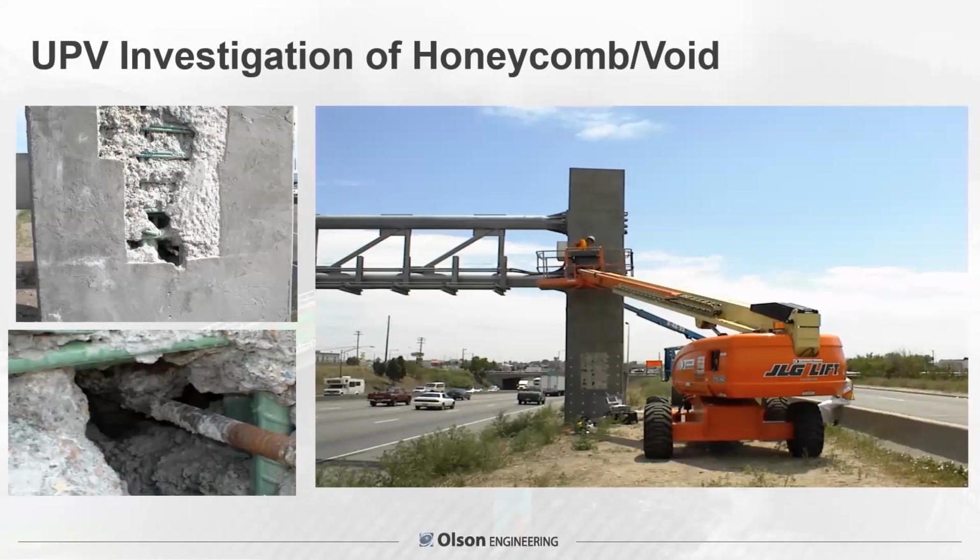So 33-foot tall, 5 by 5 foot section holding up a large cantilever highway sign out over an interstate. So this was a great concern, as you can see and imagine. You lose 5% of your density in concrete. You've just lost 25 to 30% of your strength based on a Portland Cement Association study some time back. So consolidation is very critical. I'm also on the ACI 309 Consolidation Committee.